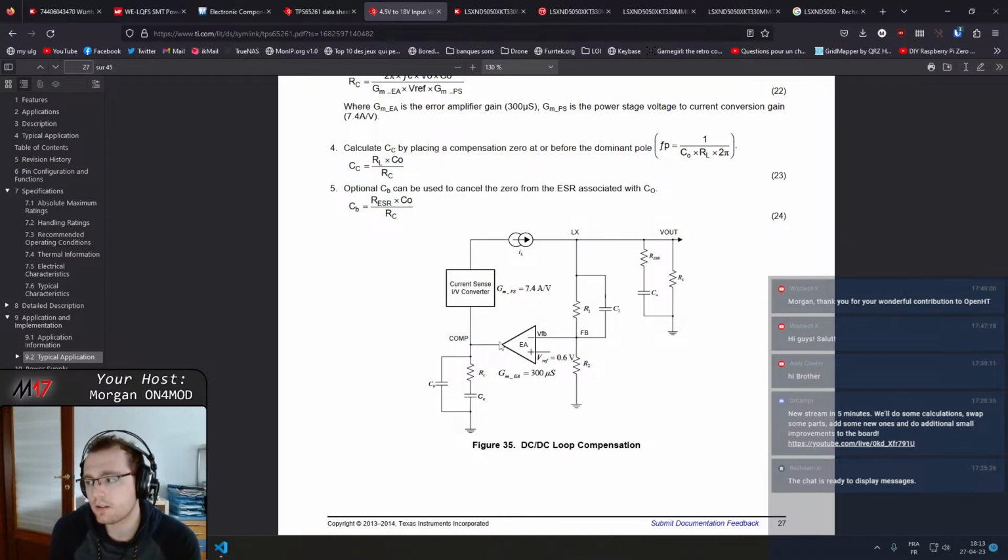So in our case, the FPGA is quite strict in terms of what voltage we should feed it. And if we supply too much or too little, it will increase the current consumption significantly or cause some malfunctions in the device. We should be careful with that.